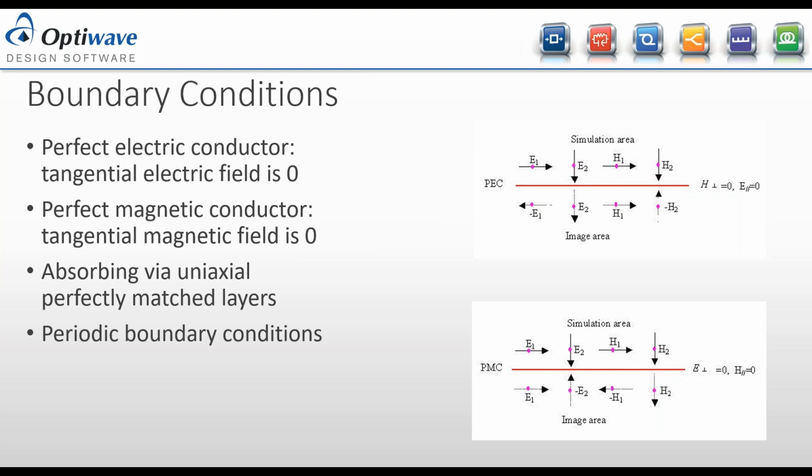So in that case, a lot of the times we'll use absorbing boundary conditions, and this is implemented through a uniaxial perfectly matched layer type boundary. I'll actually talk about this in a lot more detail in the OptiMode finite element tutorial, the mode solver tutorial webinar, sorry, tomorrow. But it's the same type of method to do it, and there's a lot of ways to think about it.